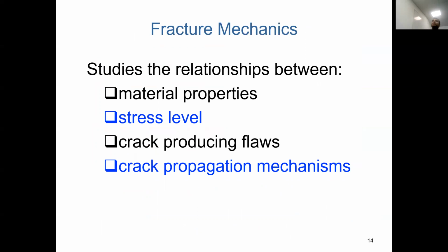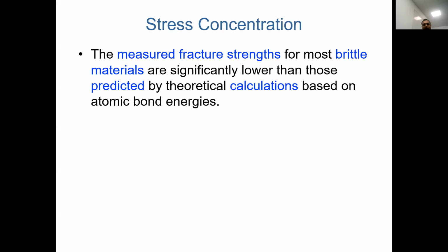When we study the fracture mechanism, we study based on the material properties. We also study based on the stress level. We also study based on the crack production, like how the crack produces the flaws and how the crack propagates, intergranular, transgranular, and so on.